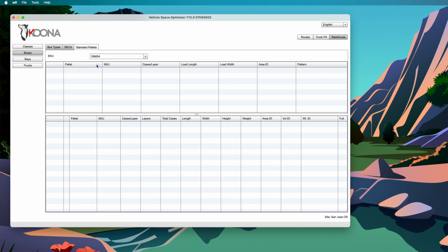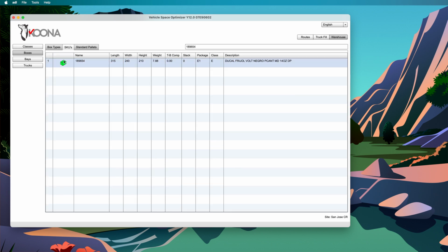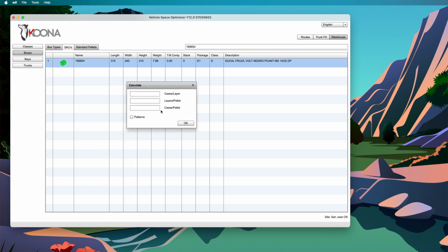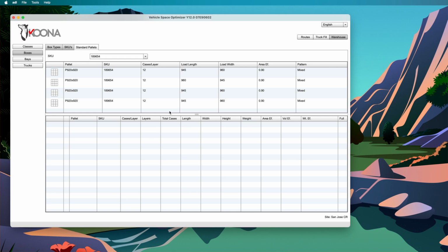and go back. Our third example will show how to use the patterns option. We click on the checkbox that says patterns, and we see that the other ones have been disabled, and we click on OK. So this shows some patterns, pallet patterns. We have lengthwise and transversal boxes. In this case, those are the only options that we have.